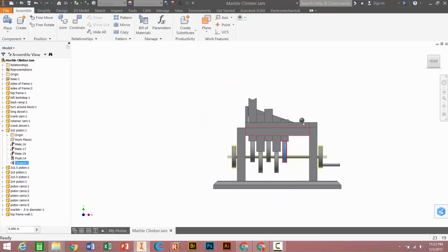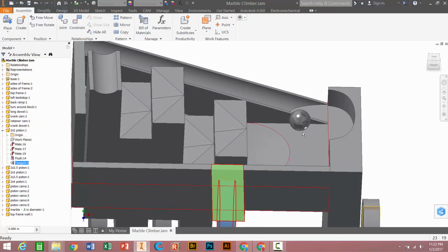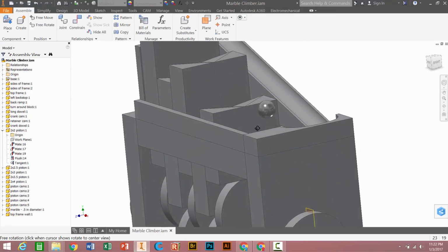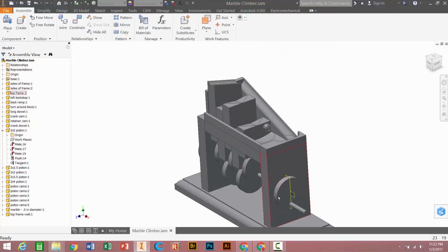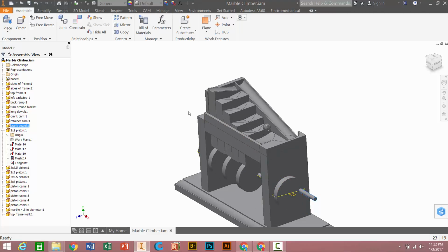And you want your marble positioned pretty much right here, so it's above this area. Actually, we may move it a little bit closer to that bowl shape. Let's look at here. Yep, that looks good. With that all ready to go, I should be able to grab the handle and things move. That's a really good sign that hopefully it was put together correctly. No rotational constraints of any kind here. Everything so far is all mates or the tangent constraints.